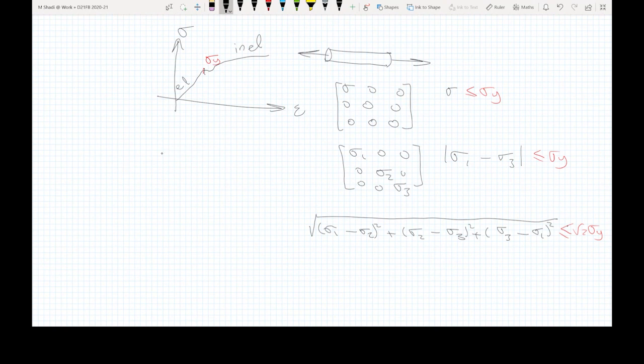So for the Mohr-Coulomb, we had the maximum stress should be smaller than the normal stress on the same plane where you have the maximum stress multiplied with the internal friction angle added to some constant we call the cohesion. Whenever this is satisfied, the material is basically in equilibrium, or the material is stable. This has not failed yet.